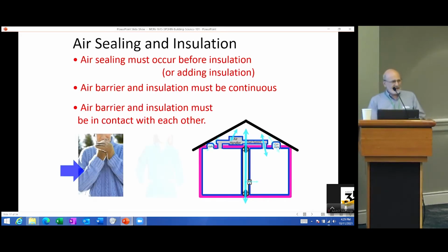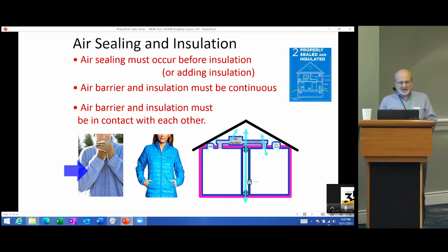There's something in the home performance industry called the pen test, the red pen test. I don't know if anyone here has ever heard of that. Basically, you understand how a structure is built and you look at its plan, or make a sketch of the plan, and then you trace around and make sure all your thermal barrier and your air barrier are continuous.